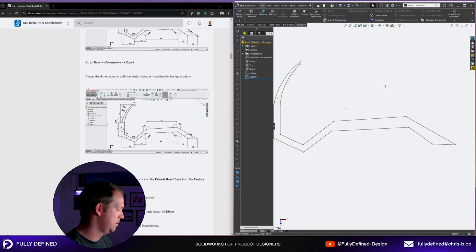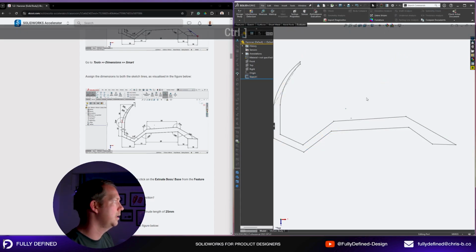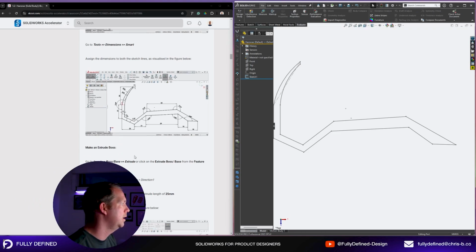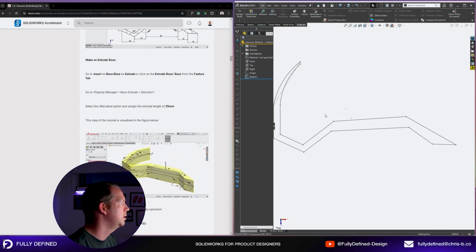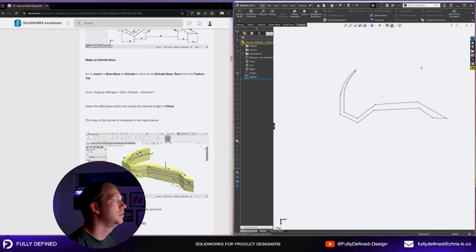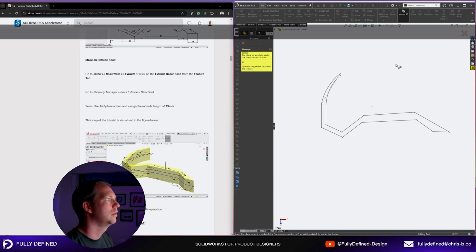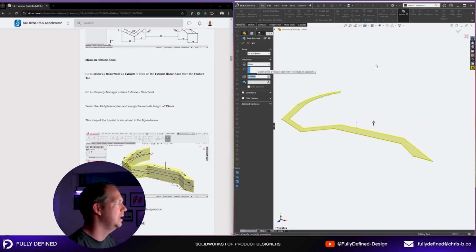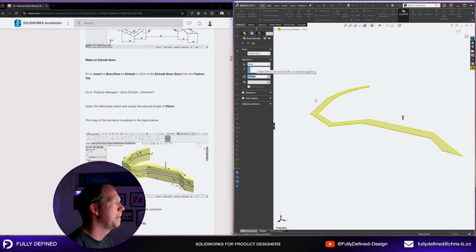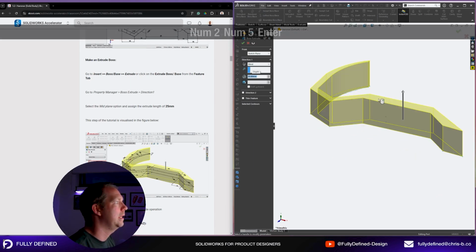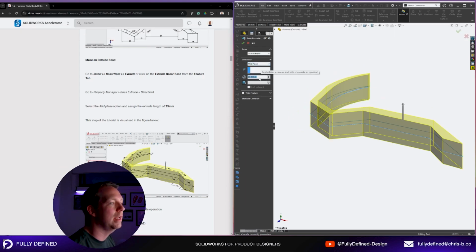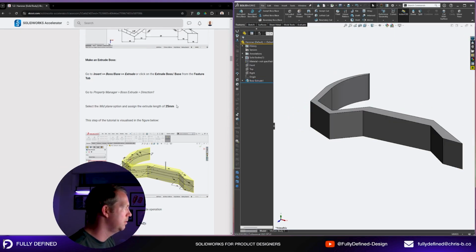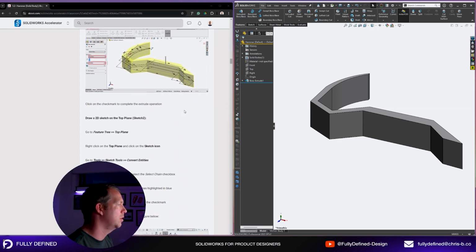Just going to save this. Okay, that's saved. Okay, now we're doing an extrude, mid-plane, 25. Now I have my extrude hotkey on my E key on my keyboard. Quite handy. And I cut extrude to Shift E. You don't have to copy, but setting up your own hotkeys is a good idea.